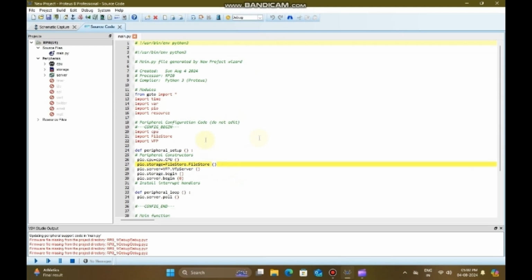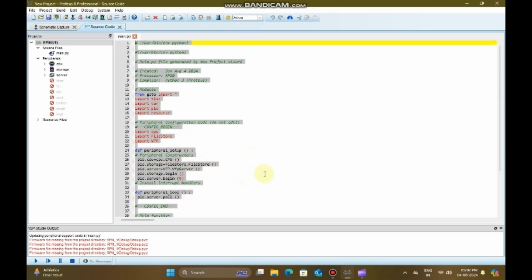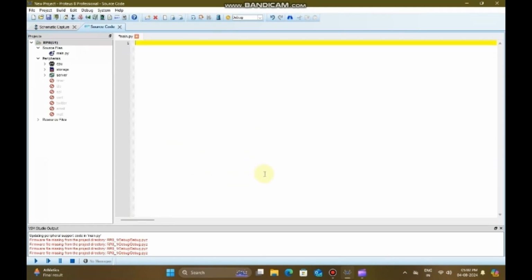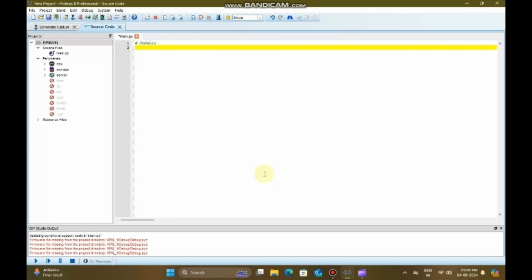After completion of schematic capture, interface programming is done on the Source Code tab. Alternatively, ready-made programming in any language may also be applied to the board by double left clicking on the board on schematic capture to assign the path to the custom program in .hex file firmware format, using Keil software, etc., if any other, for conversion.